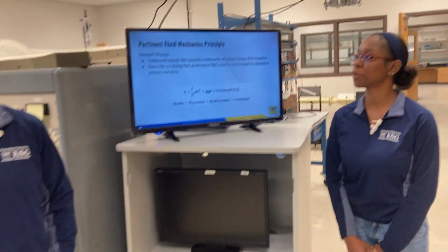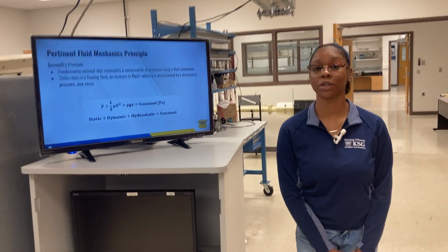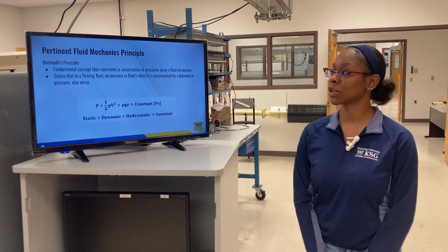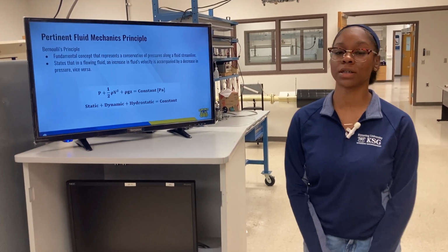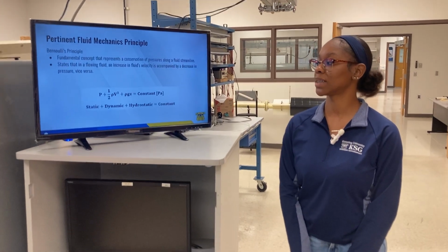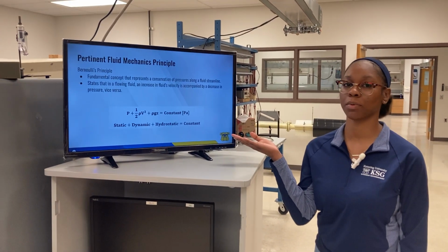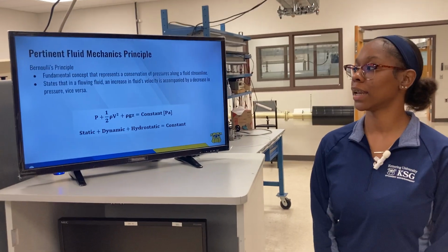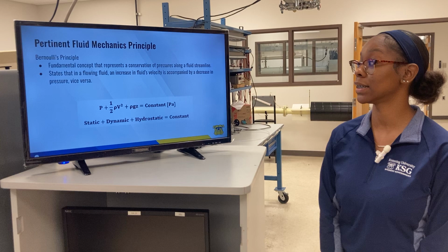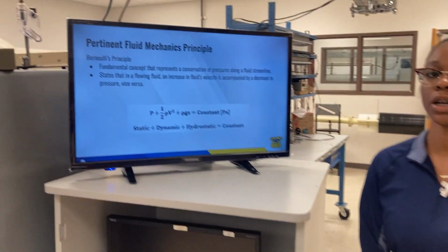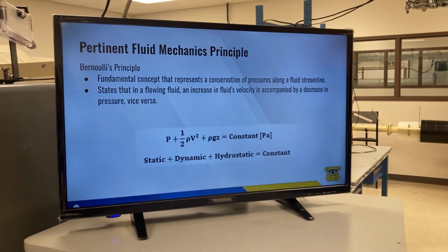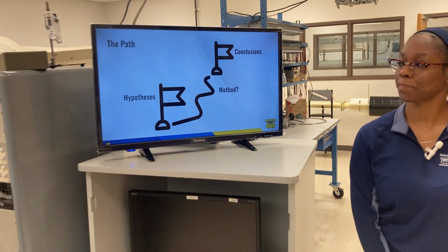So next, the pertinent principle that was used for this experiment is obviously Bernoulli's principle. This concept represents a conservation of pressure along a streamline, conservation of energy. So we have static, dynamic, and hydrostatic pressures that were constant. And it states that in a flowing fluid, an increase in fluid's velocity is accompanied by a decrease in pressure, showing that inverse relationship, and then vice versa. So, yeah.